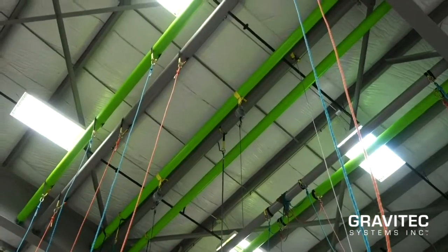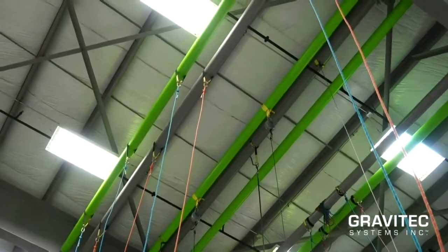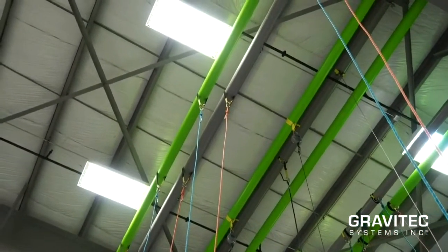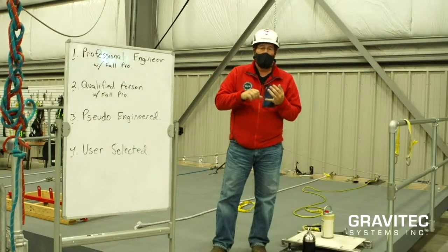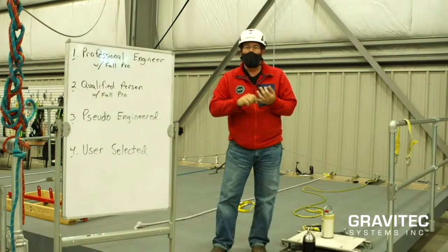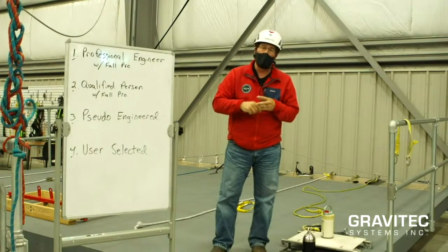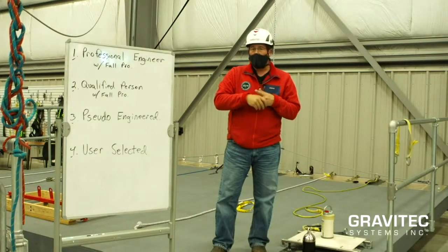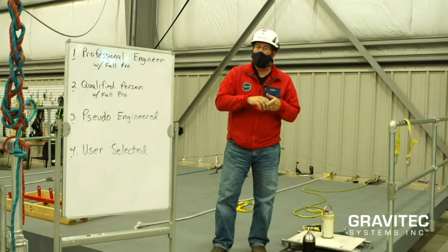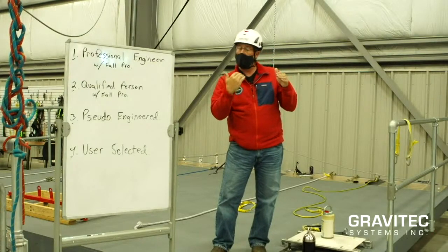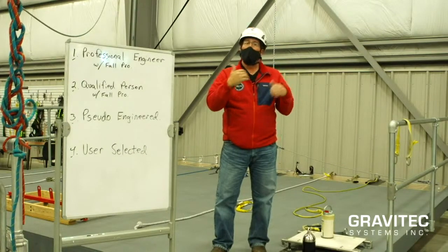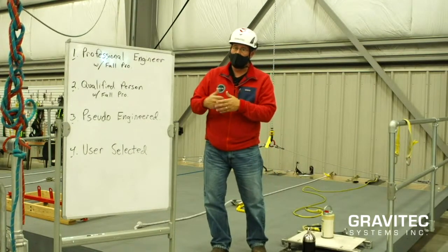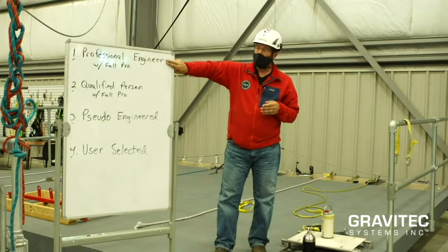We have them over top of our connex, over our rope access area, and they're littered throughout the training center. Every one of those anchors, I have a stamped drawing, I have a file with the calculations, I have a user's guide that dictates the inspection requirements, and I have a list of how many people can be connected to that anchor and what equipment can or cannot be used. That's a perfect world.